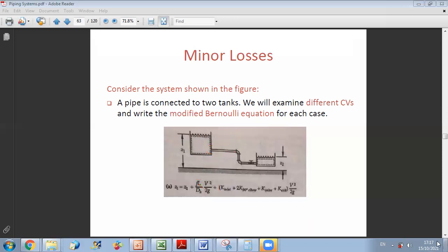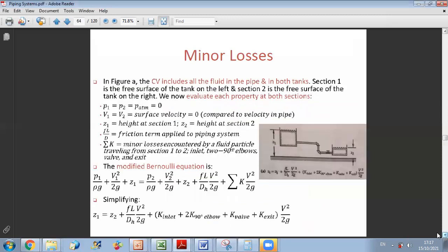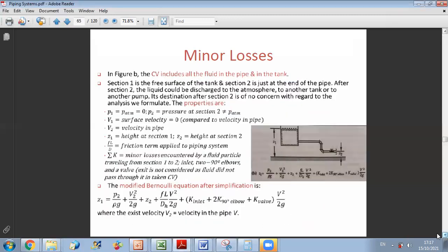Okay, so we can see then that depending on the control volume we take, we can find different things. For example, here, if you want the pressure at this point, which is in the bottom part of the dog, same procedure. This is your control volume, and now you have to account first here at point 1. You have P equal P atmospheric, V equal 0, so that you just have Z1, okay?